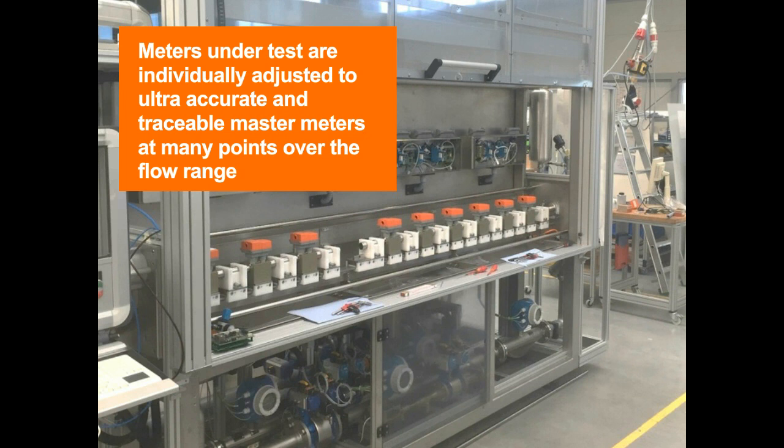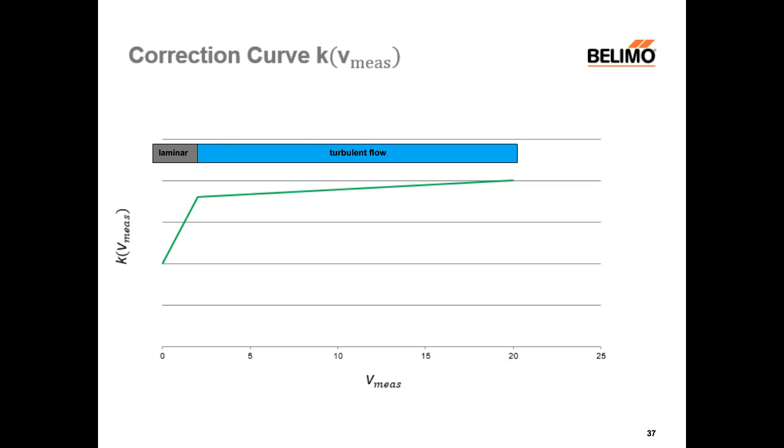You see the meters under test in the test section on top. Those are the orange ones, and you see the ultra-accurate traceable master meters in the bottom. Those are the ones we refer to. Now in the next slide, you see a schematic example of what such a curve looks like. At low velocities, we have the laminar zone, and at high velocities, we have the turbulent flow zone. And they have different correction factors.